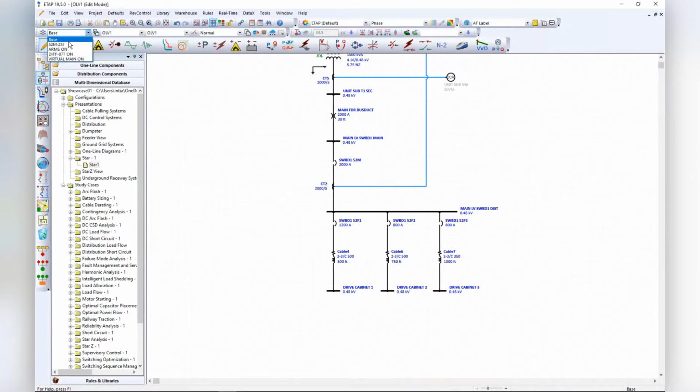And the next thing I wanna do is an ARMS zone, and that is the arc flash reduction maintenance switch in this breaker. The way you do that is, in the case of this Eaton one, they have a contact input, a relay input on the side of the breaker. You can wire to a selector switch, and you engage that selector switch. And Eaton actually sells these things already wired when you order switchgear and switchboards from them. Any equipment you order from them, you can always include those options.